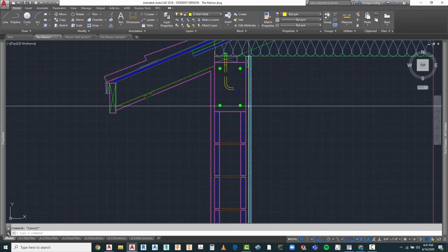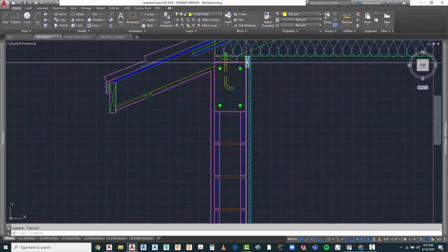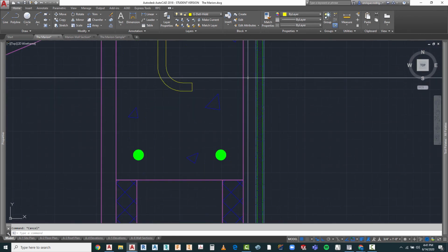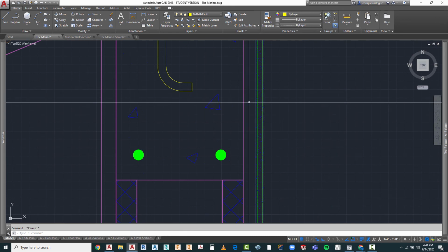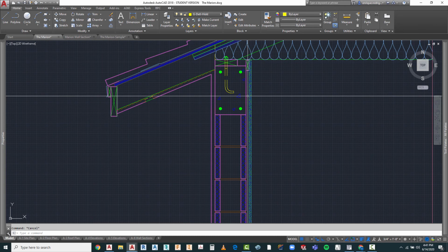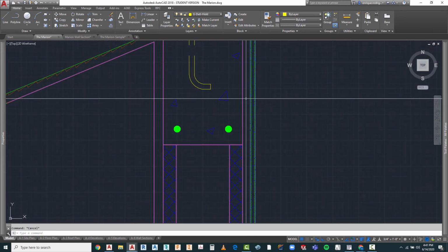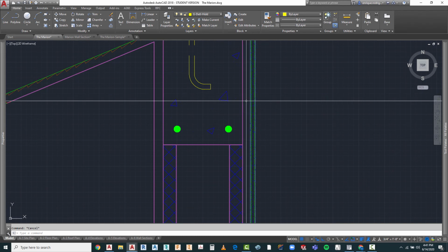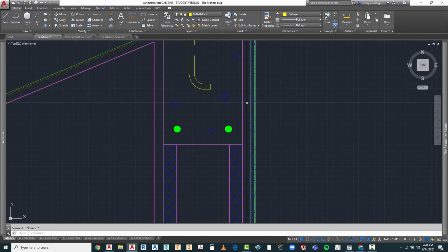Now what we've done with the drywall is actually located it. This blank space that you have in here is your vertical furring strips, and the furring strips are about every 18 inches on center. Sometimes they'll double them up. There's actually insulation, which is called an alfoil insulation.